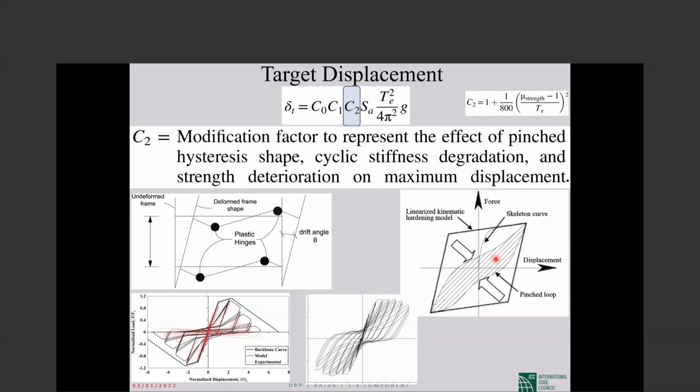If I assume an earthquake is, for example, 10 seconds, and the period of the building is 1 second, we expect 10 cycles, the length of the earthquake divided by 1. But if the period of the building is 0.1, we get 100 cycles. So buildings with a smaller period will experience more cycles in the same earthquake.